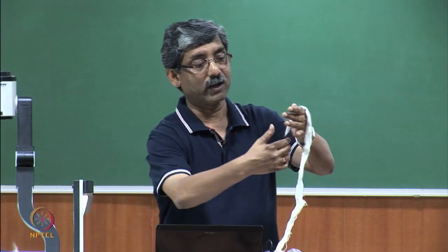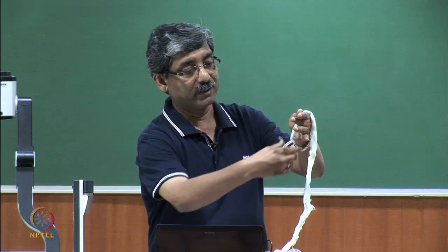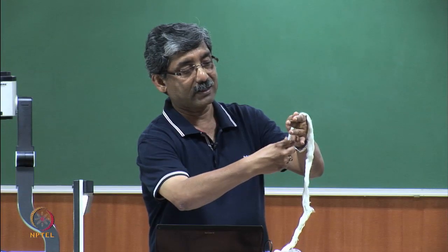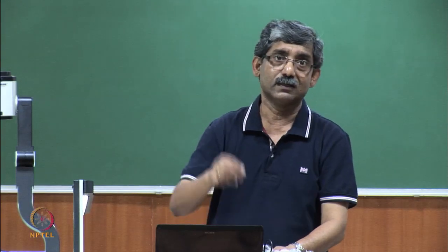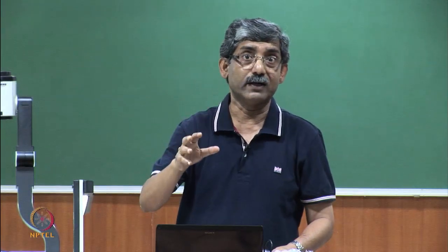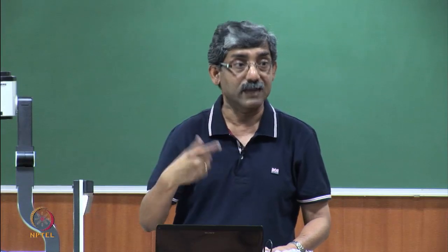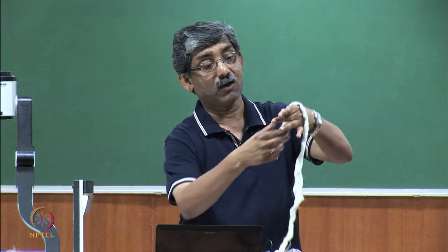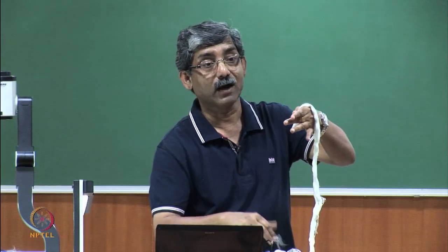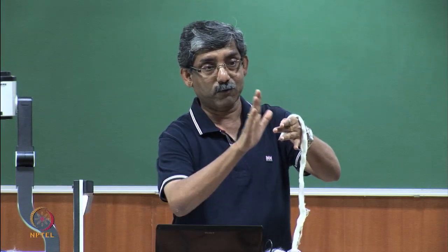So, we take out the fibers until the longest fiber is removed, at stages of 2 millimeter. Why are we doing this? Just to eliminate any chance of selecting a broken fiber, an unduly broken fiber, from the edge.